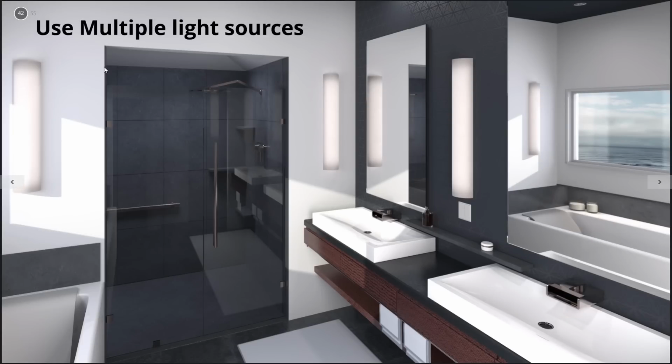Okay, another thing that will also help with interiors, use multiple light sources. In this scenario, we've got a bunch. This one actually probably has too many. But that helps with the realism, because just like in real life, you've got light coming from the window, from the ceiling, from your desk lamp, and that's going to help with the realism.